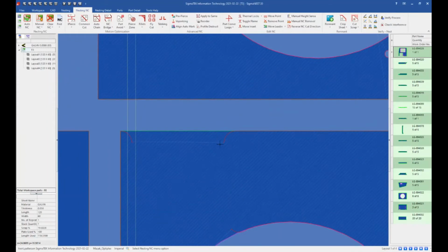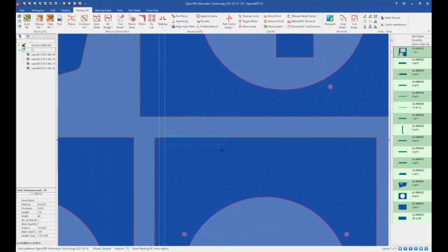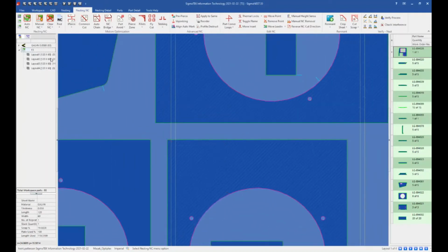Now with these recess tabs, the benefit of these is typically you're already going to be welding or adding weld into these little kind of cutouts. So it's able to get more of a clean finish without having to do any grinding or anything like that. And then it's also going to allow you to have a place to where you can put that weld in and build that part up anyways. So that's just kind of a benefit of that conditional and the recessed.